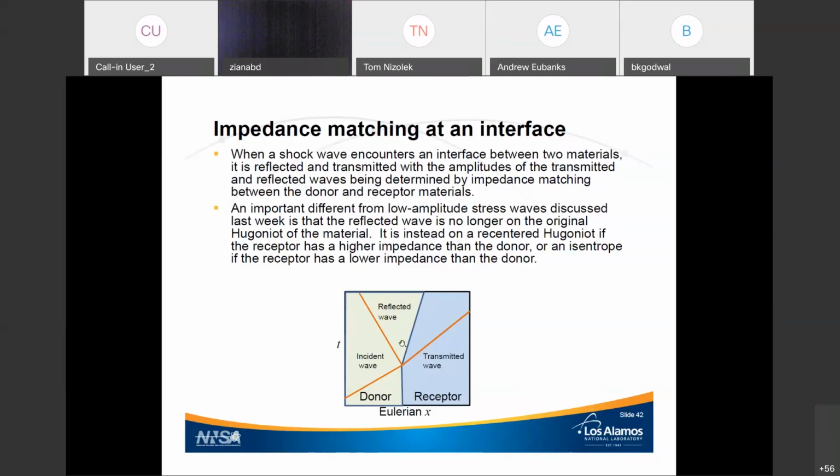Now, for many purposes, especially in non-porous materials, the principal Hugoniot, if it started off at room pressure and temperature, is close enough that you can just go from that point on the Hugoniot to the next point on that same Hugoniot, but that becomes dangerous. So you have to be a little careful.